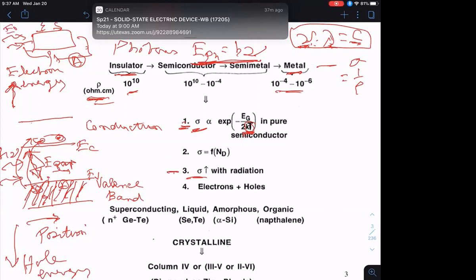So this is my electromagnetic radiation shining on this photodiode. Okay, and then I can bias it and have an ammeter hooked up to it. And this, in fact, is a kind of device that you have in your garage door openers. Okay, if you look at your garage door opener at home, you'll see at the very bottom, you'll have a laser at one end, and at the other end that you can't really see is a photodiode. And the way it works is, if you stand in the path of the garage door opener, you'll be interrupting this light source. The resistance of the photodiode would increase, and that will prevent the garage door from coming down. So very simple devices, okay, based on photodiodes.